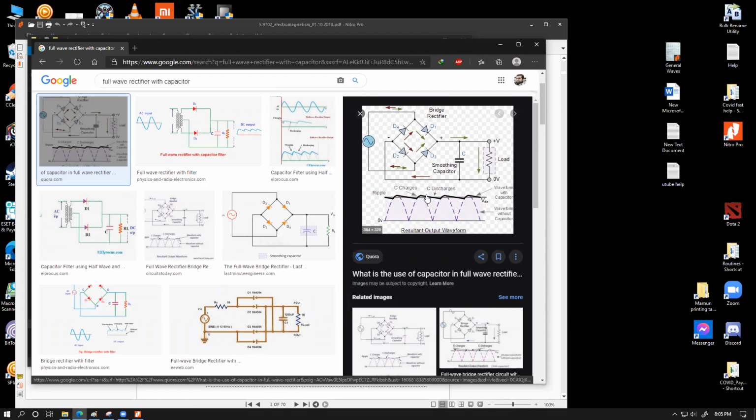What you said is absolutely correct, except for a small part. I would not prefer to use the term that the capacitor makes sure that there's a constant voltage output, where "constant" is a pretty hard term. But what is better to write is that the capacitor provides less varied voltage to the load, less varied, because whenever you introduce the capacitor you still have ups and downs.